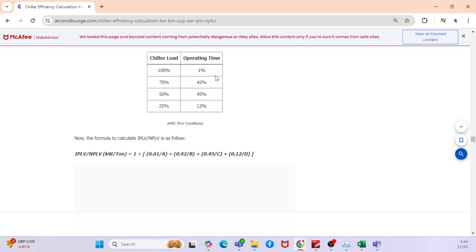So you have to differentiate the building load. Based on that you can apply diversity. Sometimes you may not apply diversity; sometimes you may go with 100 percent. I will tell you one more case.